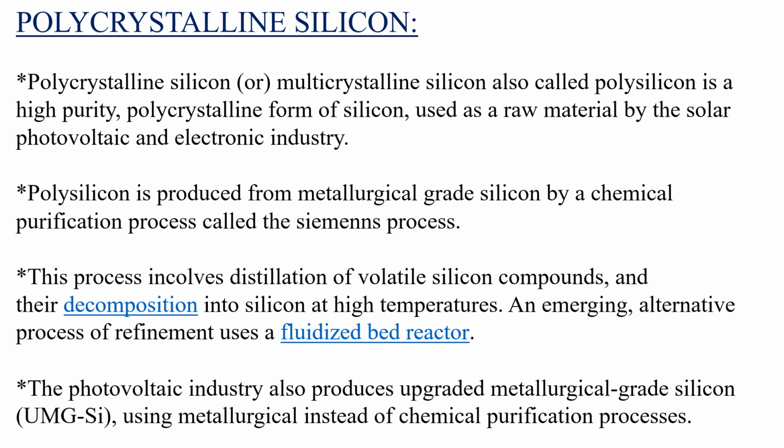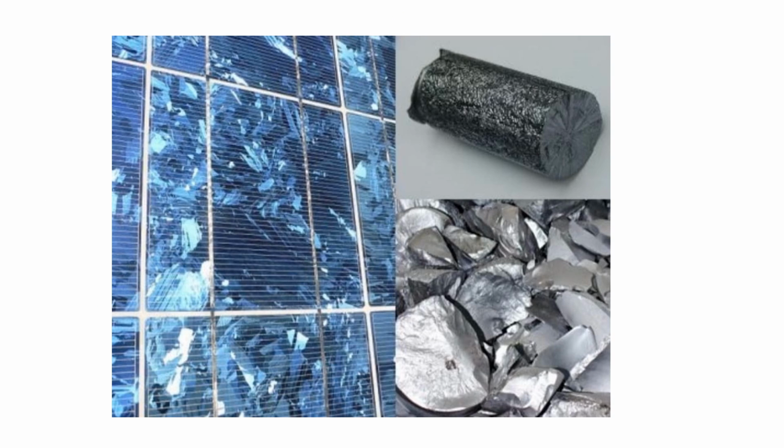The polysilicon feedstock, large rods usually broken into chunks of specific sizes and packaged in clean rooms before shipment, is directly cast into multicrystalline ingots or submitted to a recrystallization process to grow single crystal boules. The boules are then sliced into thin silicon wafers and used for the production of solar cells, integrated circuits, and other semiconductor devices. So this is an example of a polycrystalline solar cell.